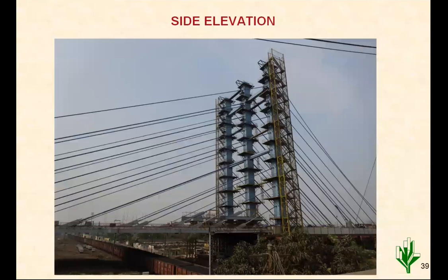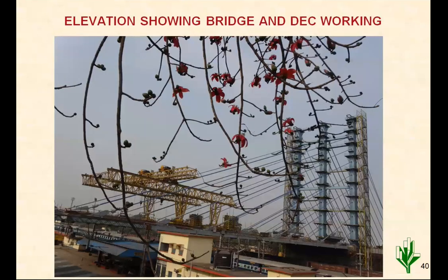This is another side view of a bridge during construction. Deck erection crane during the operation over the platform. You will find that the trains are moving below and the erection activity is going on very smoothly, because there is nothing to be fed from below and there is no disturbance to rail traffic. Only during the movement of this crane to the next position, some power block as well as rail traffic block was taken.